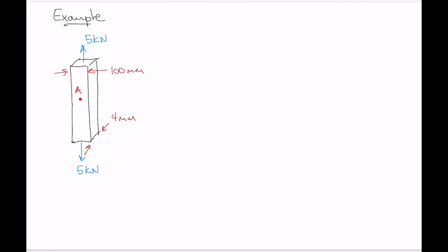So to draw Mohr's circle, steps for drawing Mohr's circle. Okay, so the first step here is to define the stress state of the element that's located at your point of interest. So that's what we worked on in the last lecture, defining the stress state of the element that's located at your point of interest.